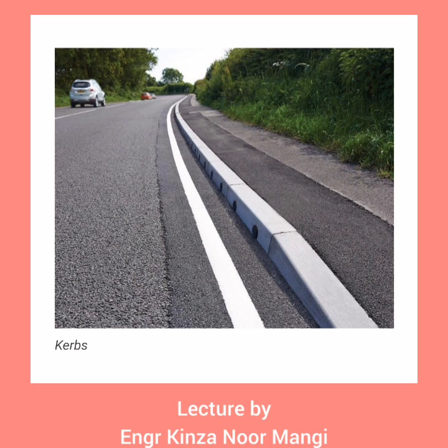They are provided when there is a considerable amount of pedestrian traffic. They are placed at a height of 20 cm above the pavement edge with a steep batter. They are generally constructed of cut stone or cement concrete slabs. The curb and the road surface near the edge together form a side channel which carries rainwater that comes from the road surface.